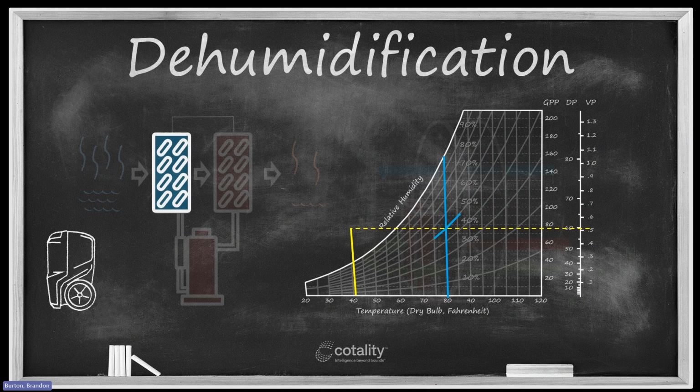That tells me that if I cool to 60 and below, I'm going to start running off of the psychrometric chart. As we continue to go below 60 degrees Fahrenheit, the amount of moisture that is in the air at 80 and 50, rather, no longer fits in that air. That's the moisture that begins to sweat out of the air. And the more we cool below dew point, the more condensation we get.